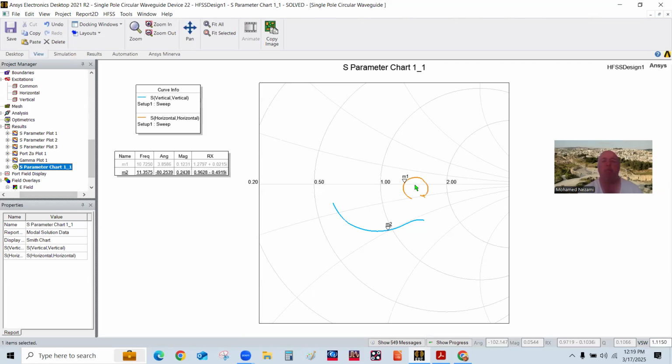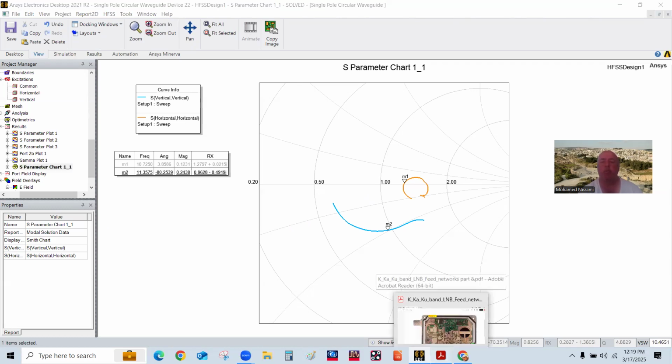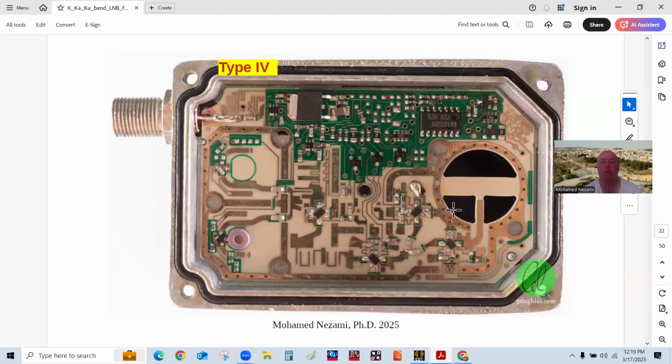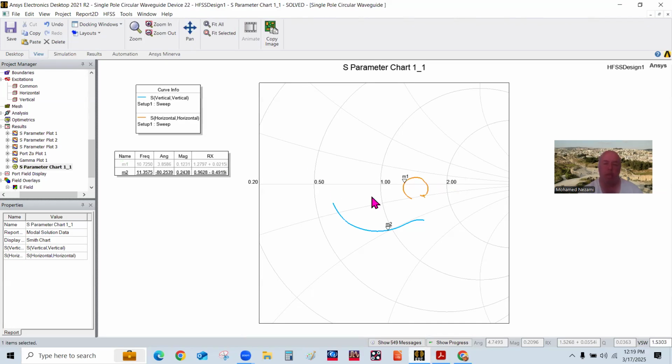And then these will become the source files for the LNA device that I'm using for these LNA GaAs FET devices. So I take these LNA devices, and then the gamma opt. Basically, I design the impedance that you're seeing here, transform this to the gamma opt that presents the transistor, makes the transistor behave with the minimum noise figure.